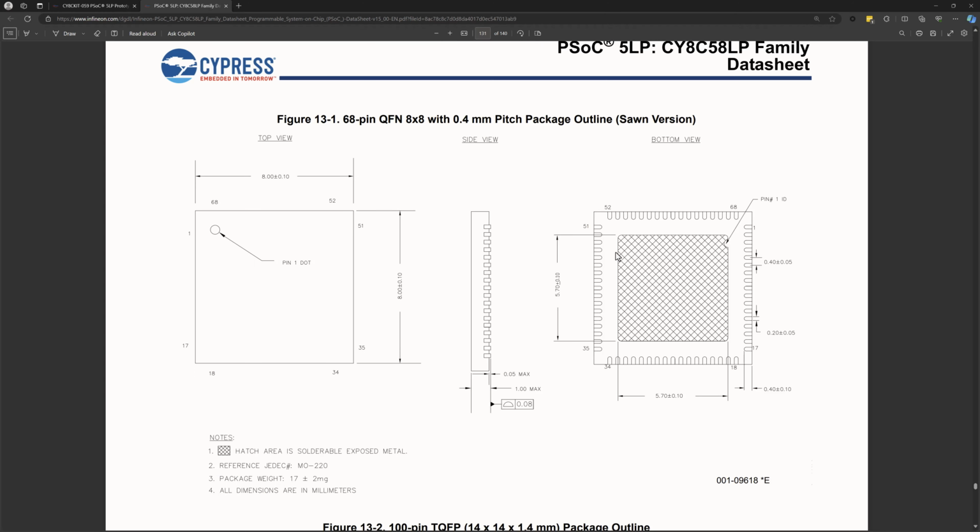A couple of things with this: this is going to be a new soldering challenge for me. I've not tried to really solder these types of QFN packages before. And something else I have done, and I'm definitely looking for feedback on this: when I look down here at these, we're looking at 0.2 millimeter for these connections, and I've defaulted on my PCB to 0.254 millimeter.